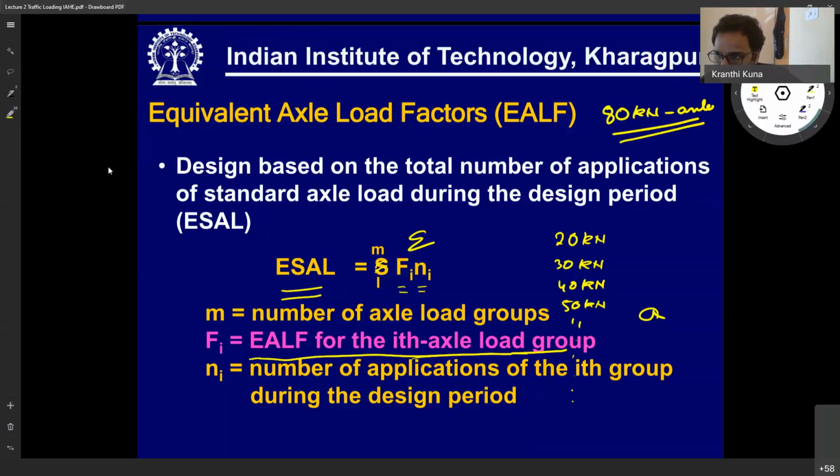So what about the national highway codes? Do we calculate the rutting thickness and the modulus of elasticity? No, for national highways, they have to follow IRC 37, isn't it? So they have to run the IITPAVE analysis, layered elastic analysis, and obtain the strain and input it in the performance models and get the life of that pavement. Okay, sir. Thank you.